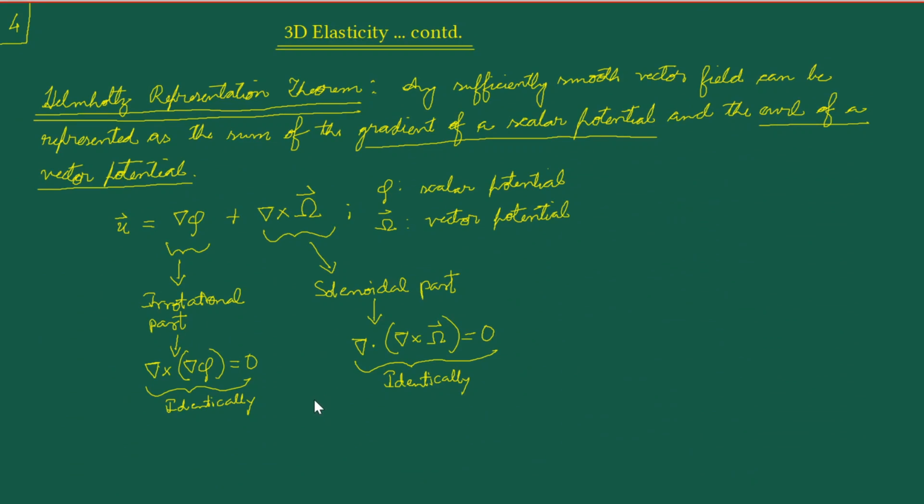Now, if we actually do these steps, that we substitute the linear elastic isotropic material behavior for the sigma in terms of the strains, and then express the strains in terms of the displacements using the strain displacement relations, then the differential equation that we are going to obtain is basically this.